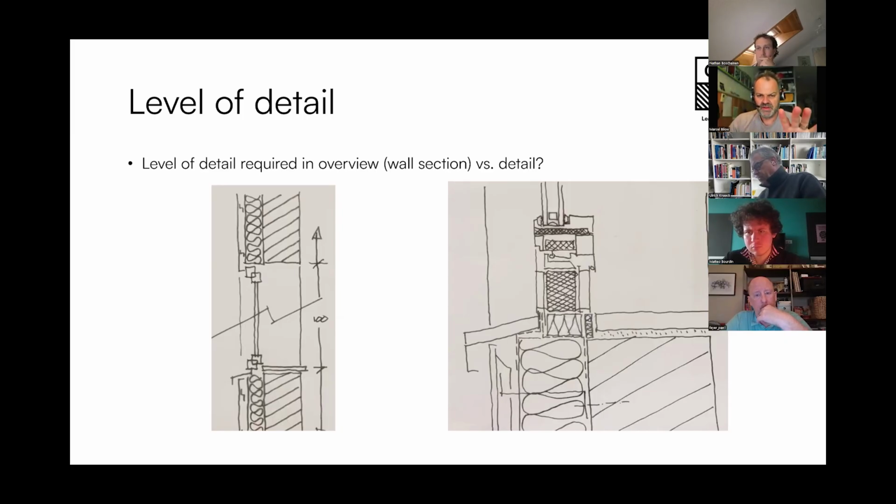Each part you use is already on the correct layer that defines the materials, and you can easily draw or place a window or a rectangle over your detail and then hit the button for thermal calculation, and it shows you a false color graph of your isothermic lines, and you know exactly if you have a thermal bridge or not. Quite a powerful tool.